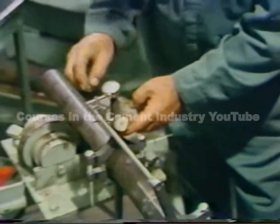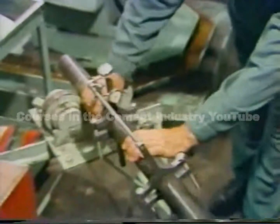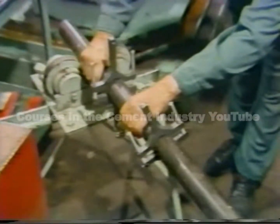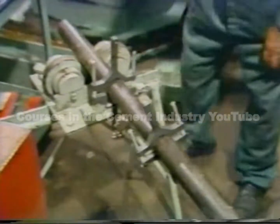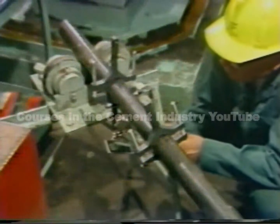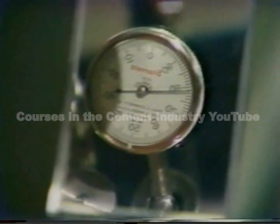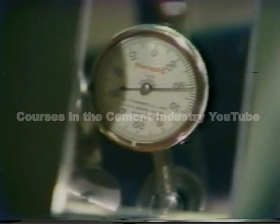Because of the way they are mounted, the sag will only show up on the dial indicator mounted on the top. So that's the one to be concerned with. The indicator has moved backwards from 0 to 79 thousandths, which means it's a negative 21 thousandths.